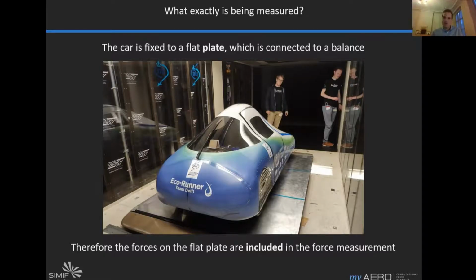So it's the car that's fixed to a flat plate, which is fixed to a force measurement apparatus. So that means that any forces on the plate are also included in your force measurement. I mean, this is obvious to everyone working in the wind tunnel as well, because they also do a run without the car, with just the flat plate, and they subtract the two of them. But they don't account for the intricate interactions that happen between the car and the flat plate, which turn out to be very important.